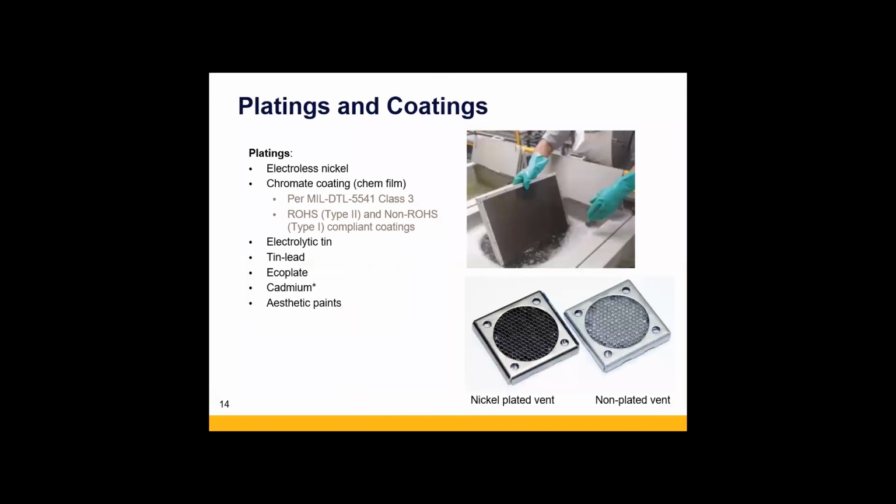One downfall of that is the two-layer will reduce the airflow. Omni-cell can be a great option in many cases, but for applications where an omni-cell construction won't work because of your space constraints or your high attenuation needs, you can achieve the same effect by plating the honeycomb. The plating of aluminum honeycomb in this instance will bridge the non-conductive node and eliminate the directional effect of the honeycomb. It's also a much more thorough coverage, which results in better shielding.